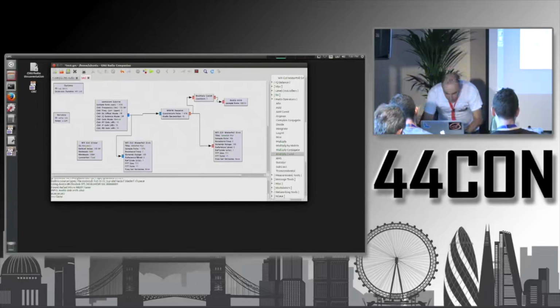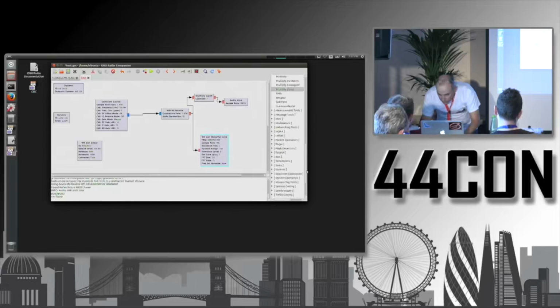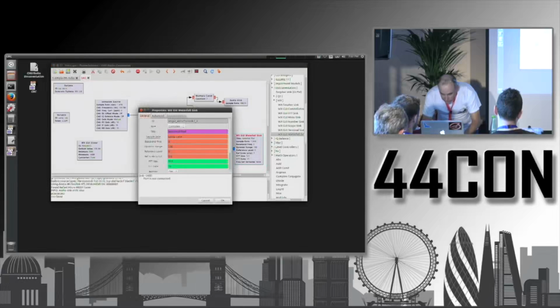I'm going to drop this one here because I'm going to put in another one. So this waterfall for the RF signal, I'm going to drop it. And I'm going to add another one for the audio. So this one here, the changes you have to make: float, and sample rate, you replace it with 48,000, 48 kilohertz.